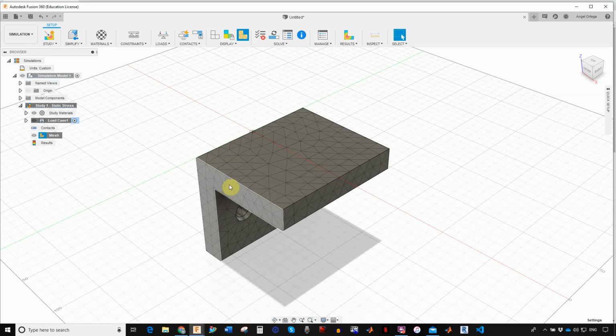As you can see, there's a lot bigger gaps between the mesh, right? Now for something like this, since we're going to do a very simple type of study, the mesh doesn't have to be super fine. Something between 5 to 10% should be good enough for this type of simulation. The accuracy should still be there, so we should be good. So there's my mesh. We've covered two things so far: the materials and the mesh.